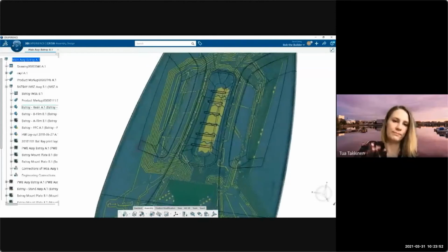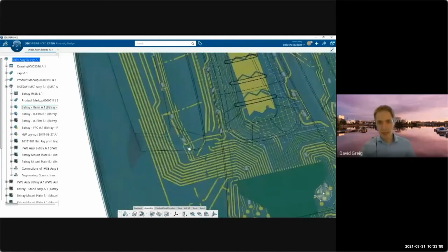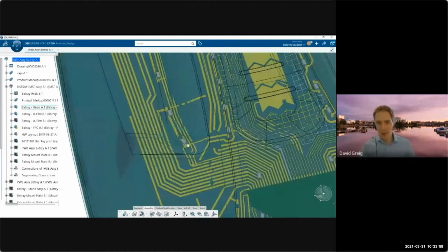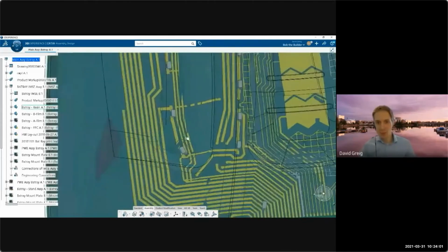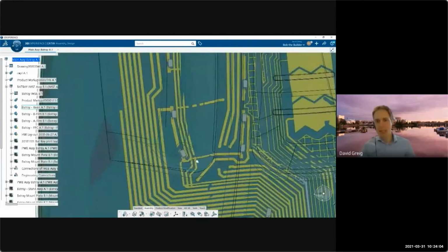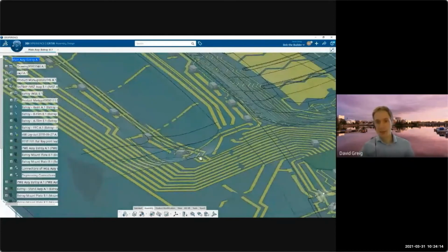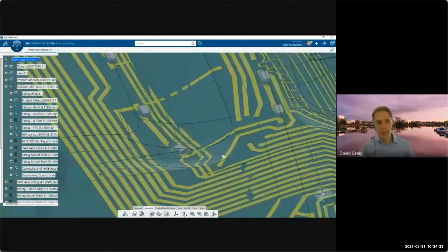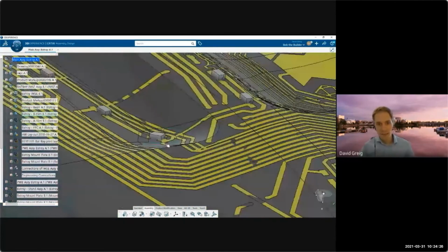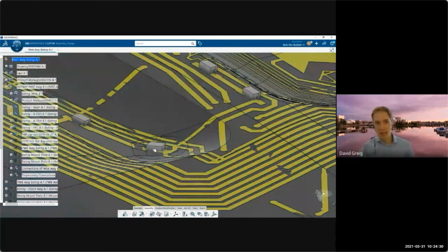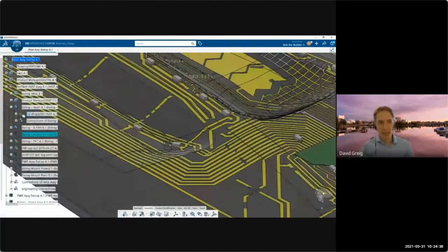Okay, so this, I guess, is the area that everyone's sort of indicating down here. The LED, if you see my mouse, was rotated, and that was moving into this sort of 3D shaped area that we need to flatten out. If we kept it as the regular 3D shape, when we actually mount this LED onto the film, it's not going to adhere properly. It needs to have a completely flat surface, or else it can pop right off during thermal forming. But we can come right in here, let me move the resin here, and make that nice and flat just in this one localized area, while keeping everything else exactly how it was, the resin unchanged.